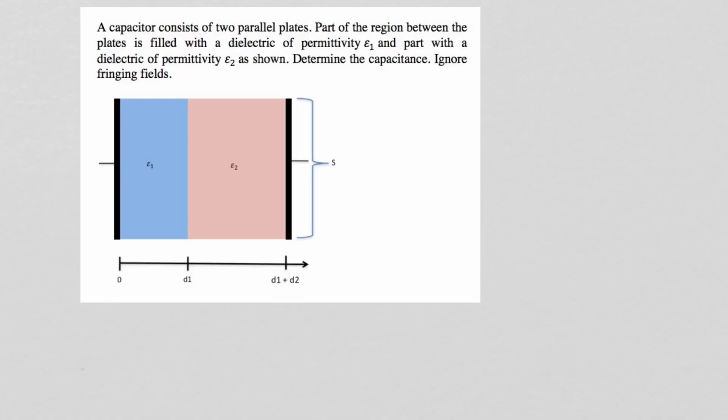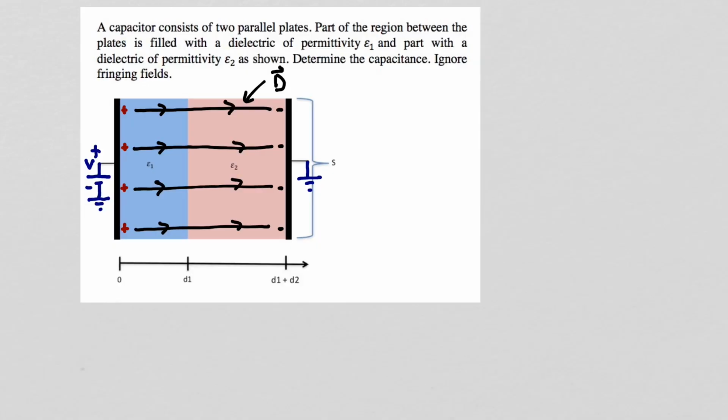This way, you will develop a greater understanding and mental model for the charges involved, the resulting fields, and the capacitance of this structure. When we apply a voltage across the capacitor, charge will develop on the plates. That is free charge, and the only place in this structure we will have free charge. Electric flux density begins on positive free charge and terminates on negative free charge. So the electric flux density field will be the same in both materials.